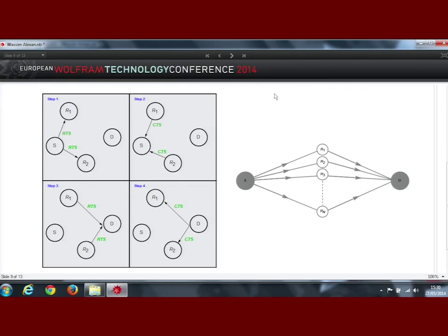At this point, the relay nodes would do the same. They would send the training sequence to the source node, repeating the same procedure for all nodes in the cooperative communication system. This allows any two given nodes to estimate the channel fading coefficients between themselves at any given point in time.